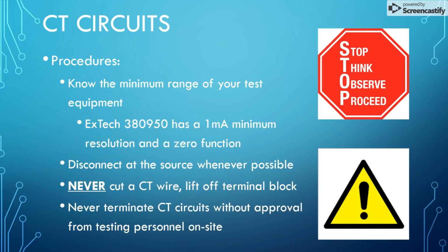We always disconnect at the source whenever possible. So we never cut a CT wire in the middle; we lift it off a terminal block. And lastly, we don't terminate CT circuits without approval from testing personnel on site.